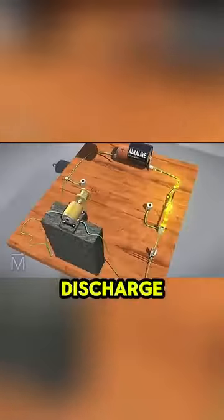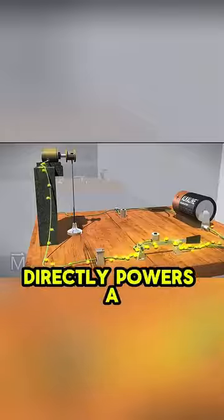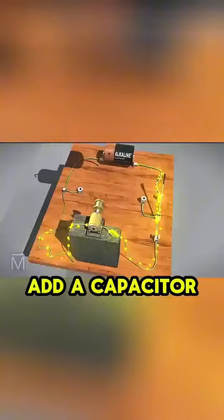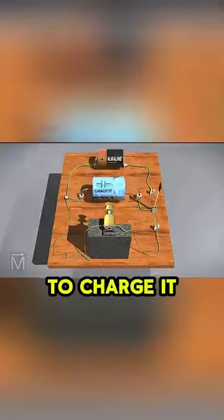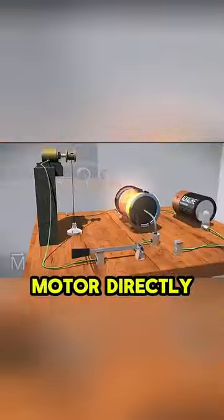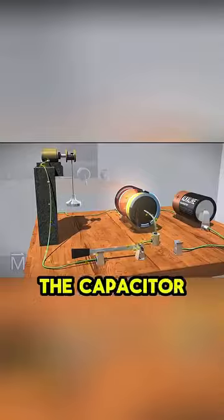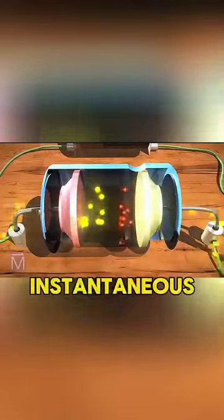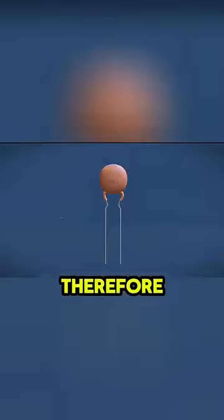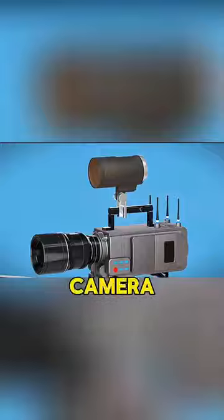Furthermore, a capacitor's discharge speed is much faster than a battery's. In this setup, a battery directly powers a motor, and its rotation speed is slow. Now, if we add a capacitor, first we use the battery to charge it, then we switch the circuit to let the capacitor power the motor directly. You can clearly see the motor speed has increased a lot. This is because the capacitor provides a much larger instantaneous current than the battery, giving the motor a greater power output. Therefore, capacitors can power devices that need fast charging, like the flash in a camera.